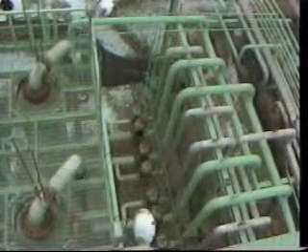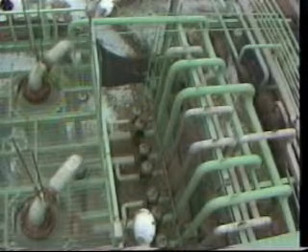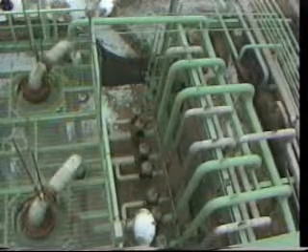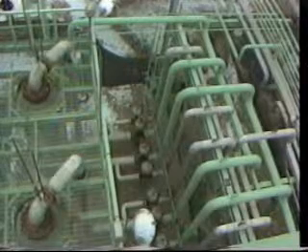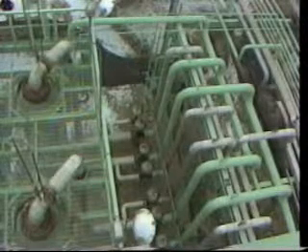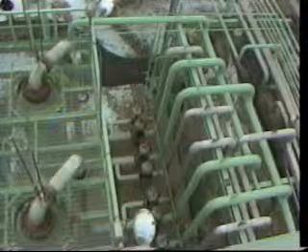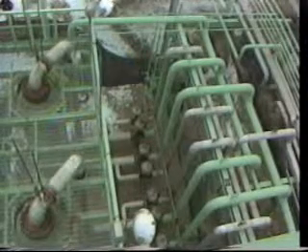The diaphragm valve, often termed a motor valve, has found many applications. Because of the various lining materials that can be installed, this valve type has widespread acceptance in the processing industry, wherever corrosion and abrasion may be a problem. This type of valve can either serve as a shutoff valve or as a flow control and throttling valve. You must become familiar with the design application of these valves, as well as dimensions and strength data, when designing a flowline system. These concerns must be considered to prevent safety hazards and costly mistakes.